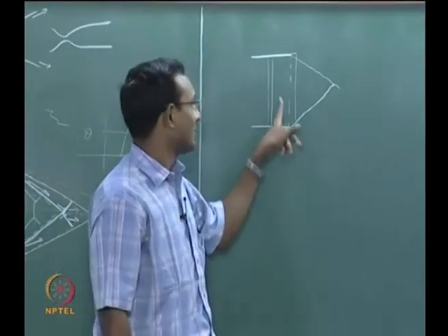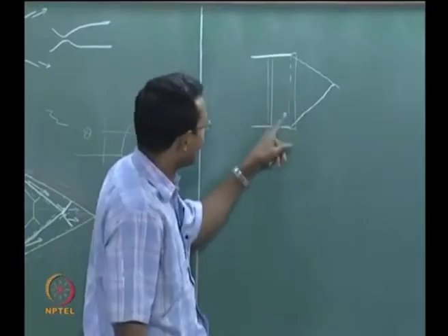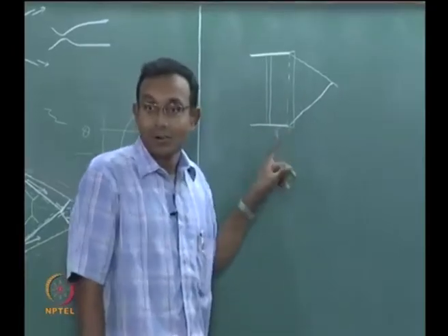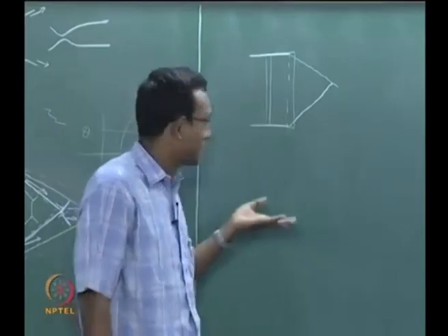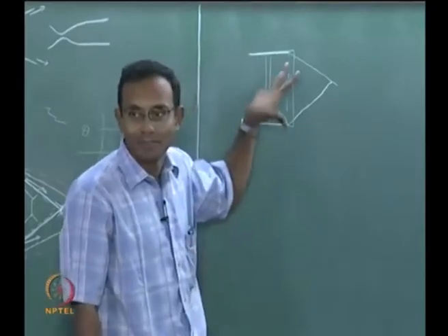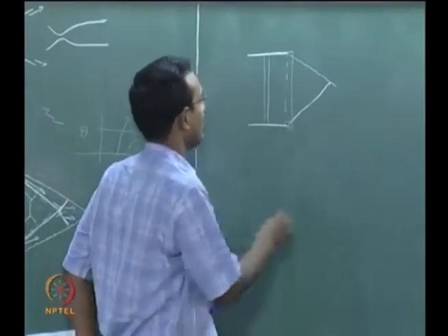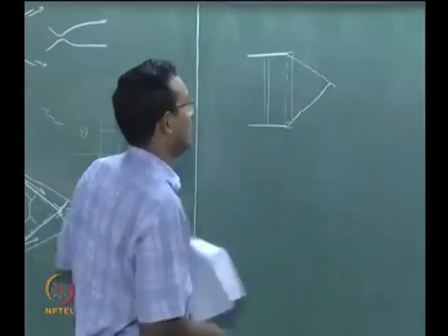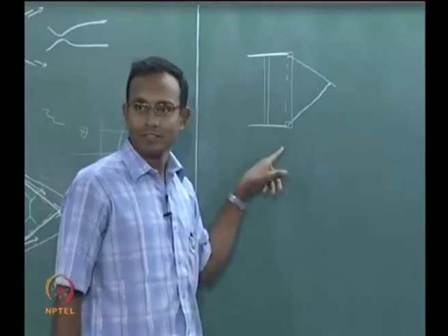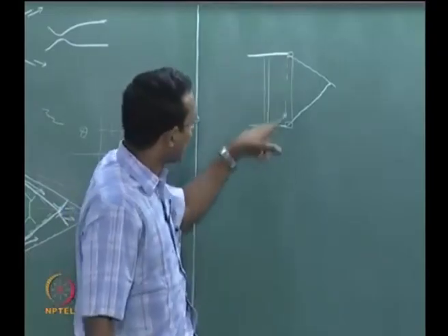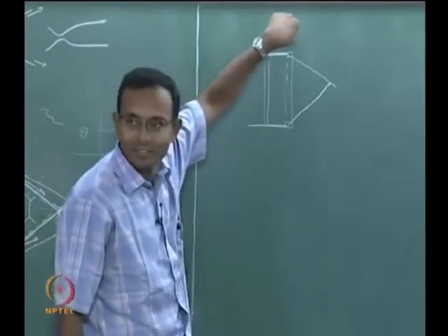So this pressure is higher than this inside, so it is seeing a higher pressure. What is it? It is suddenly pushing, it is like a piston suddenly pushing against the fluid slab there. So there will be a shock that is forming, and what is the job of each of these shocks formed? They have to go and tell all the fluid that there is a pressure jump there, okay.